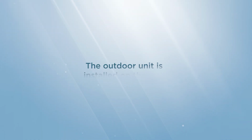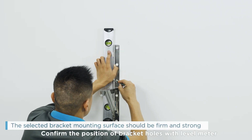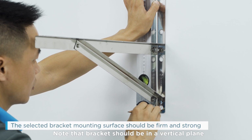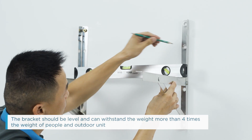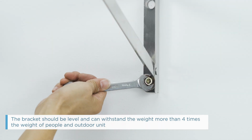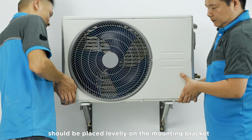The outdoor unit is installed on the wall. Confirm the position of bracket holes with a level meter. Note that the bracket should be in a vertical plane. Fix the mounting bracket of the outdoor unit. The bracket should be level and can withstand more than 4 times the weight of people and the outdoor unit. The outdoor unit should be placed levelly on the mounting bracket.